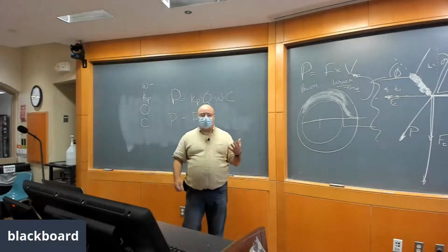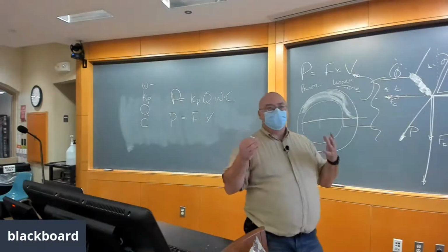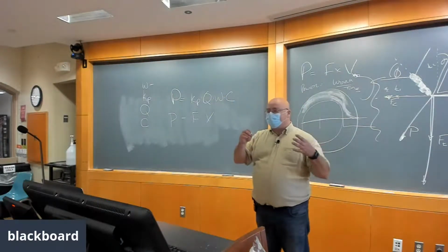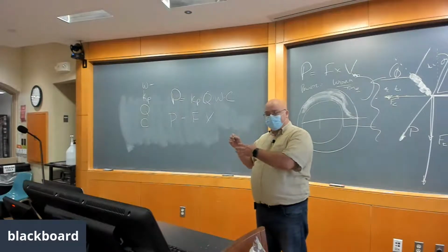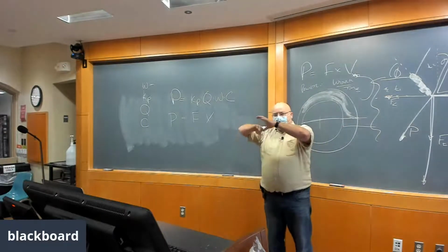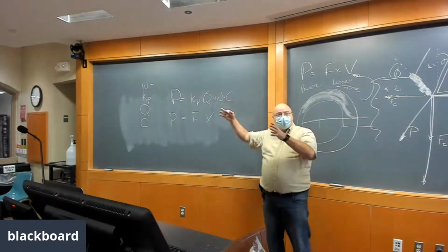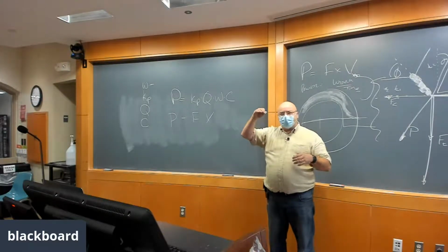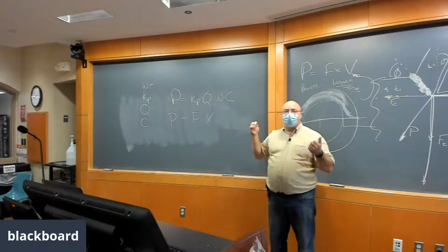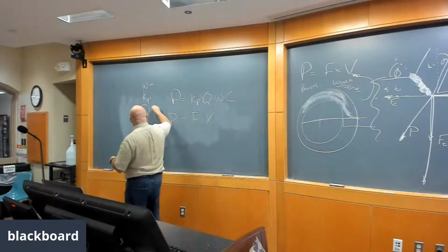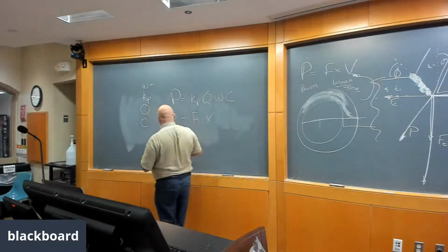In this feed factor, they again determined experimentally when they did their model, and the graph of the results didn't quite match the graph that they expected, right? That often happens in experimentation. When you do a model, you get a graph of what the results should look like. Then you do the experiment and you get a graph that's sort of like the graph, but not lined up correctly. They figured out that there was this factor that depended on the feed rate. And so they had this formula to figure out what's this feed rate factor. And so again, you look these up in the machinery's handbook. It'll allow you to estimate power.